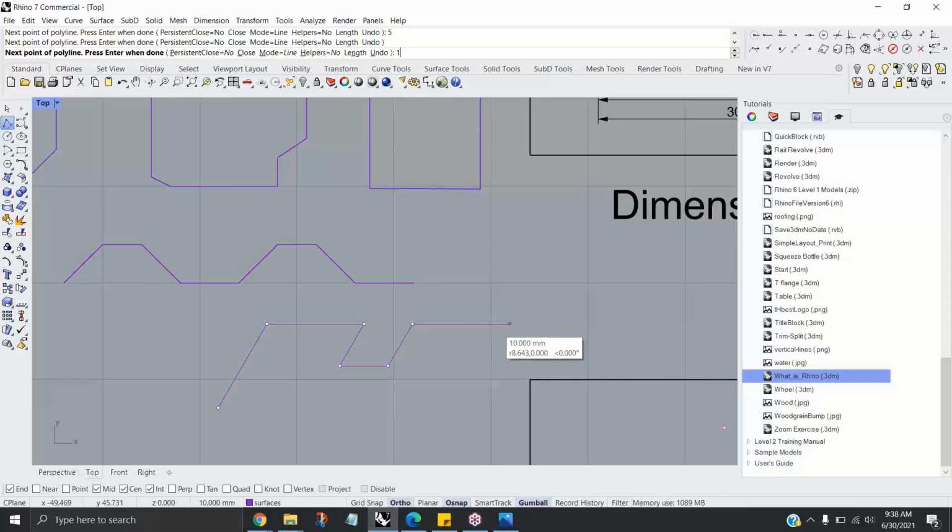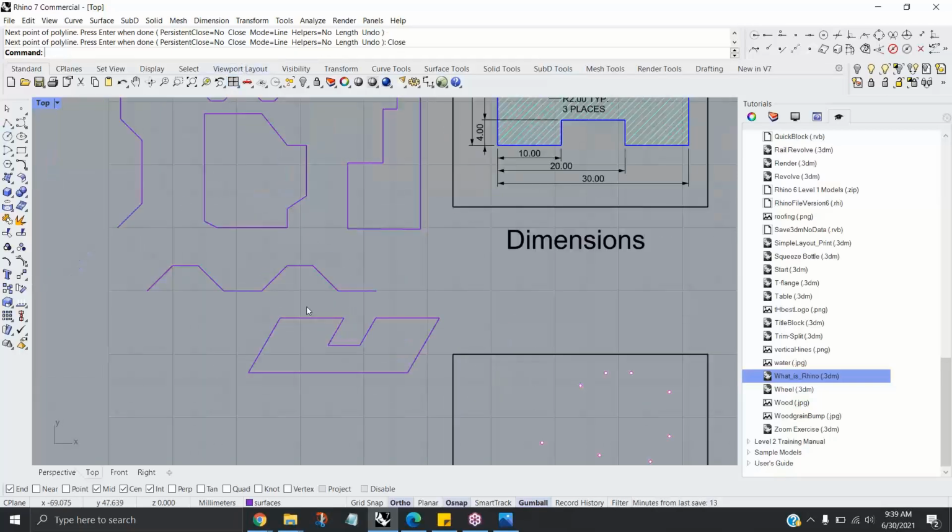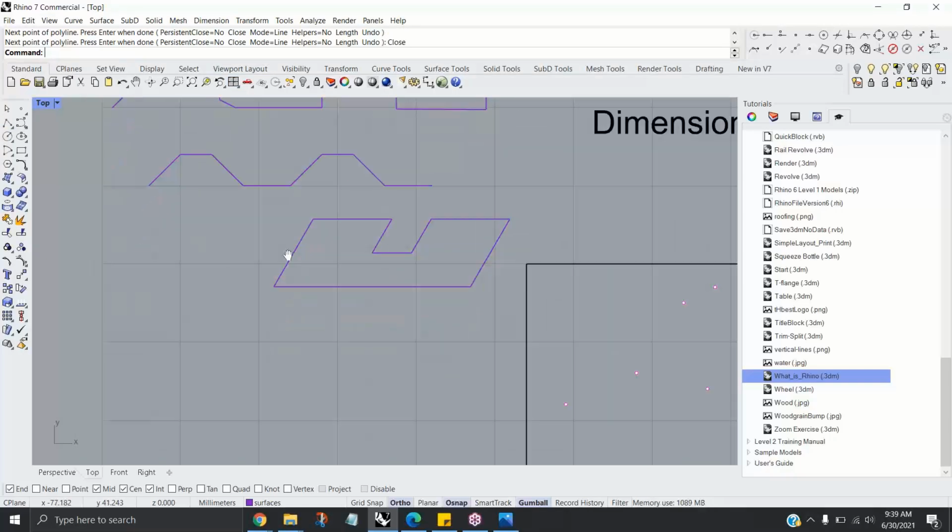So this is called distance constraining, and it involves locking onto an angle, which ortho's helping us with, typing in the distance like 10, and then enter. And after it locks you onto the distance, if you don't like 10, you could type in 5, or I'll go back to 10. And then you have to pick to lock in that distance. So that's called angle constraint.